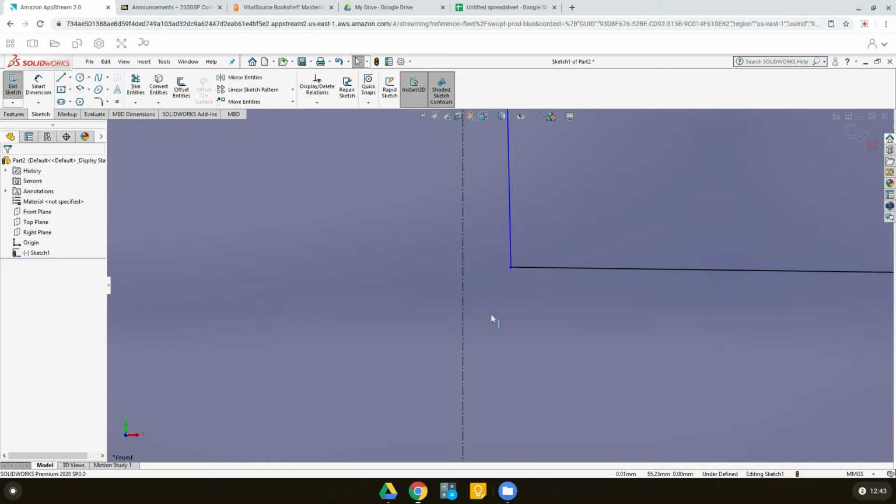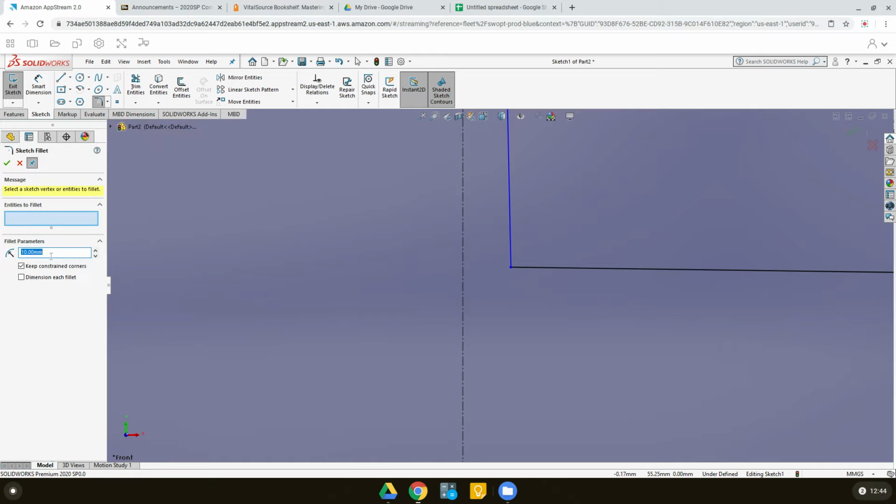Now, because we don't want any sharp edges, because that's not good. Mechanical stresses tend to get accumulated at the sharp corners, so we need to fillet that out. So I'm going to use the fillet option. Fillet radius I want to be 1 millimeter. It's a very short fillet there, 1 millimeter between this vertical line and this root circle.